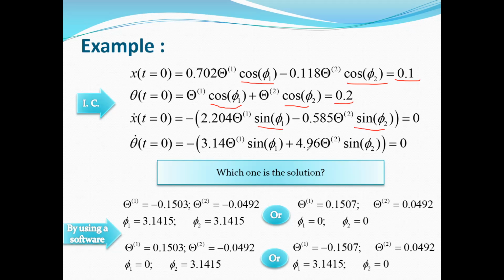Generally in multi-degree of freedom systems, these coefficients are not as important as the natural frequencies and the mode shapes. As I told you in the first session, we usually use the mode shapes and natural frequencies to extract the principal coordinate system and to solve these types of systems to obtain the forced vibration response and to find a system of uncoupled ordinary differential equations.